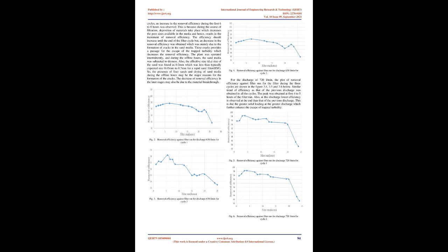Chlorinator. The water obtained after filtration is disinfected with bleaching powder solution. A chlorine doser is installed to feed bleaching powder solution from a 200 liters capacity solution tank. It is installed in the section of the pipeline from filter to reservoir. The dosing is adjusted based on chlorine demand. The chlorination process is for the pathogen removal, so, after the filtration process all other parameters except the pathogens should be under the desirable range.